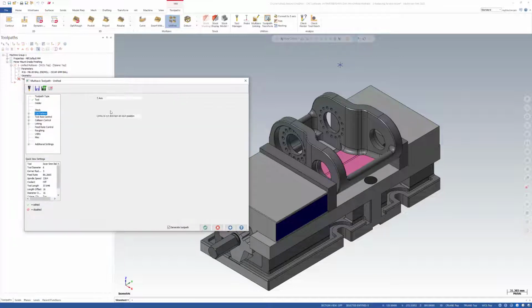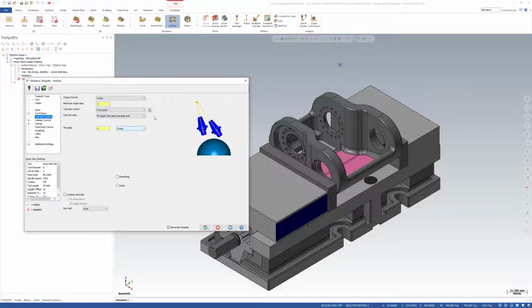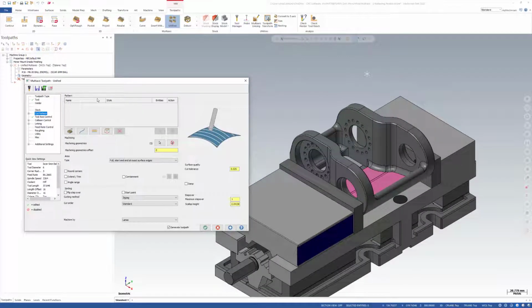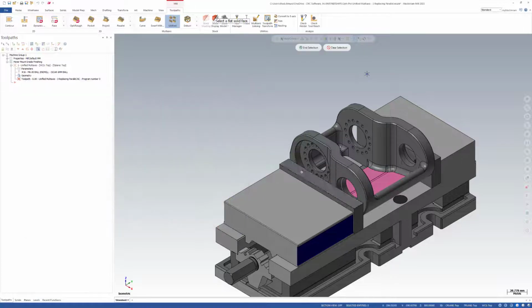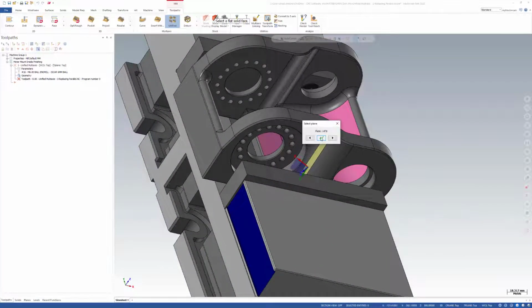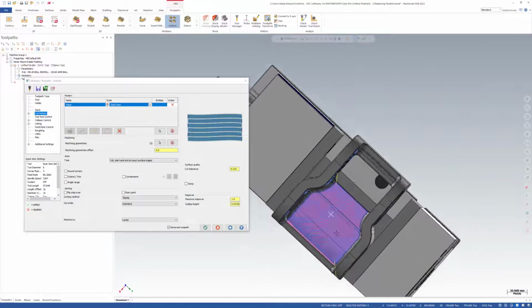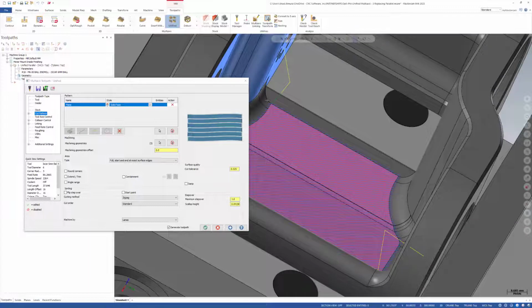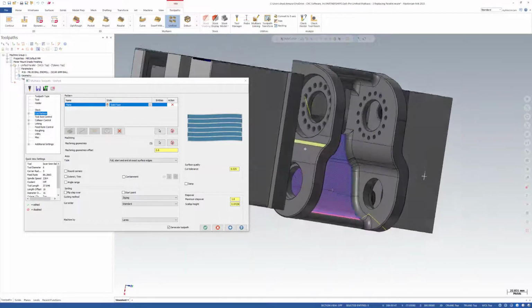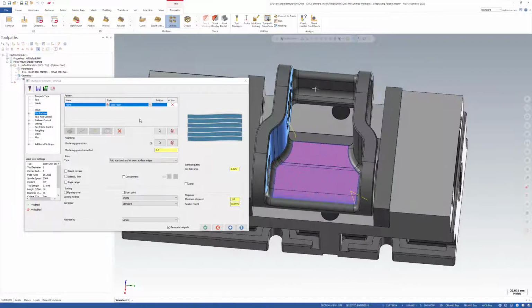And same thing as before, we have a point tool axis control. And from here, we can change our mind any number of times. So let's select a cut pattern style. Let's go parallel to a plane first. So let's say I want to select a plane, or instead of a plane, let's go solid face. Let's stay parallel to this yellow solid face here. If I generate my toolpath, you see pretty straightforward stepovers that propagate parallel to that single solid face.